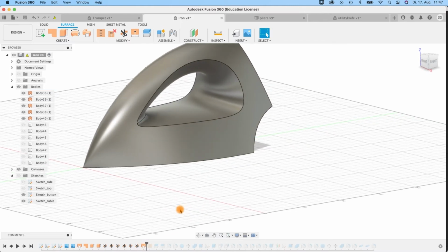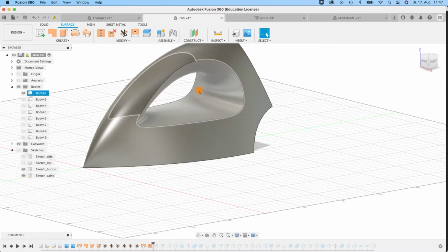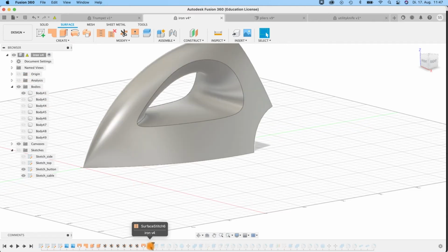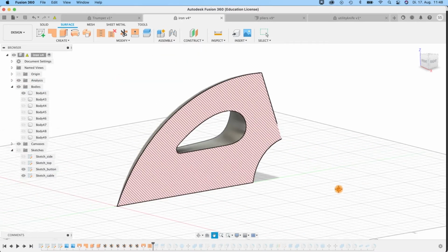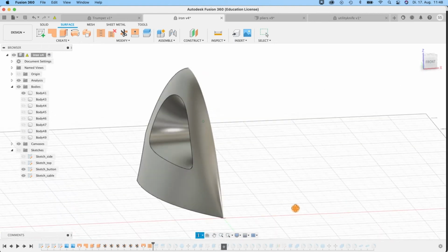So patching, it's called surface patching, so putting different surface parts together, and I can stitch them. I did this here, and you see this, now it is a solid body. There was this stitching operation where I can connect all the surfaces together, and you see here now I have a solid body, and the analysis shows my aligned colored pattern.